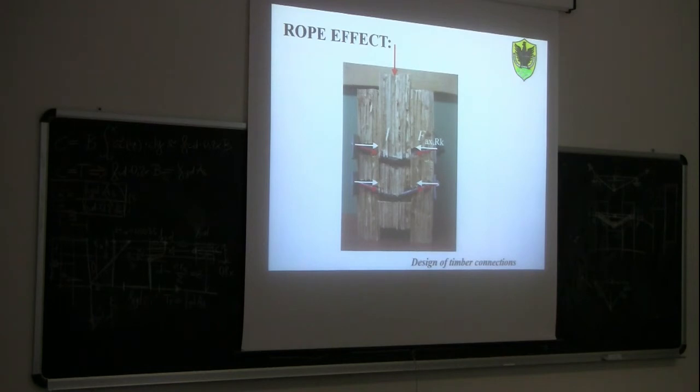Did we have friction here before if we had no steel plates? Could we count on friction here? No, because we didn't have any compression force. So no compression, no friction. Instead, in this case, we have a compression force, which could be fairly high. Particularly if you have this kind of deformation here, we're talking about quite a significant stretch. So quite a strong compression force, and a strong compression force also means quite a significant friction.